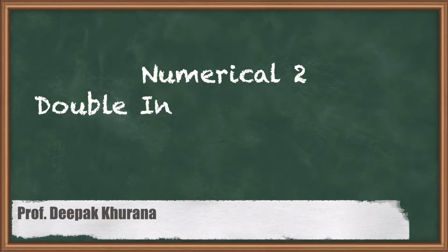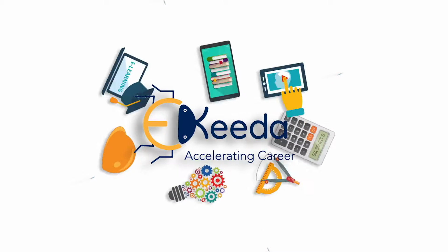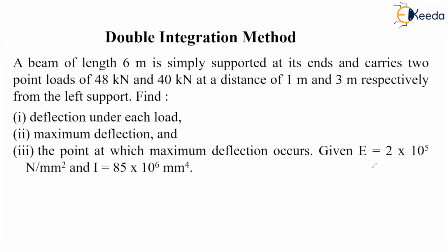Hello dear students. In this session we are going to solve a numerical on double integration method. In this question we are given a beam of length 6 meter simply supported at its ends and carrying 2-point loads, 48 kN and 40 kN, at a distance of 1 meter and 3 meter respectively from the left support. We have to find the deflection under each load, the maximum deflection, and the point at which maximum deflection occurs. The modulus of elasticity and moment of inertia are also given.